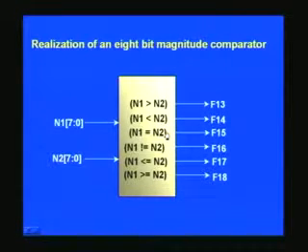So this is for equality, this is for not equal to, this you are already familiar with, exclamation mark for inverting, right, and this is the symbol for less or equal to, and this is greater or equal to, and you may get confused with this symbol later on, and they are called non-blocking statements which will be used in the always block later on. We will see more details later on, and let us see how the program goes.